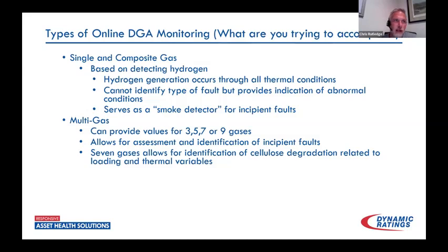So really, if you go through IEEE, there's no real guideline saying after this amount of through fault, we need to do this kind of testing. Or, to my knowledge, that's not present. And I feel like, once a transformer is in service, you have breakers that tend to slow over time, so through fault durations become longer and longer. Certain areas will accumulate more fault value than others, be that the conditions, through a wooded area, elevation, that type of thing.